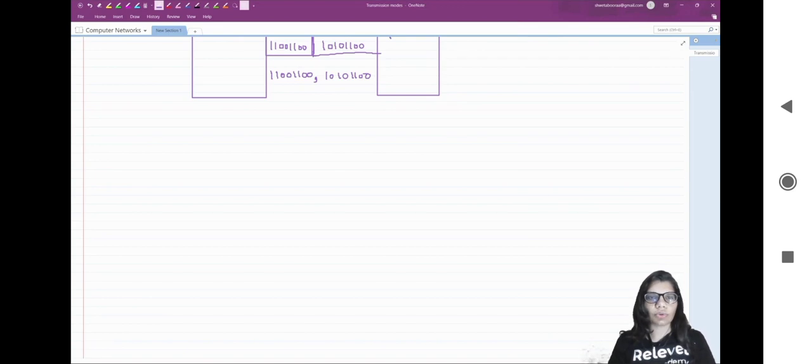Asynchronous here means asynchronous at the byte level, but the bits are still synchronized. The time duration between each character is the same and synchronized, okay? So only the bytes are asynchronous. Bits are synchronous inside a byte. In an asynchronous mode of communication, data can be sent at any point of time. The messages are sent at irregular intervals and only one byte can be sent at a time. So this type of transmission is best suited for short distance data transfer. Okay. So here if we draw an example of asynchronous,